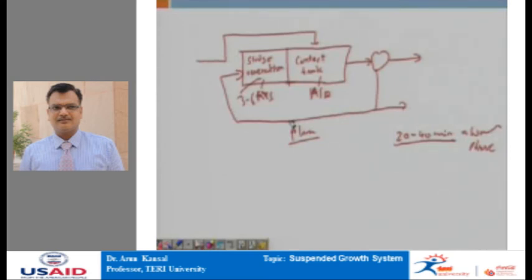The aeration volume requirements are approximately 50% of what we have for the conventional or tapered aeration plant. It is thus often possible to double the plant capacity of an existing conventional plant by simply doing some retrofitting in this form, which is shown as a layout plan. The redesign may require only changes of pipeline and some minor changes as shown.